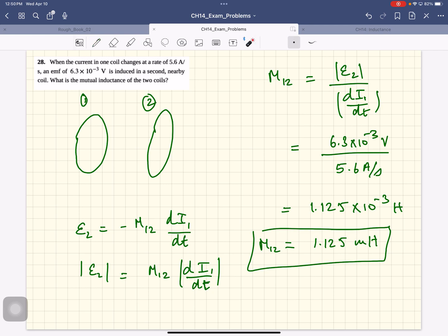And again, you guys remember, this number depends on the proximity of these two circuits. The closer they are, the bigger this number will get. Okay? All right. And so in general, you don't have a closed form expression for this. It depends on, for instance, even at the same distance, if the orientation is like this, the mutual inductance changes. Okay?